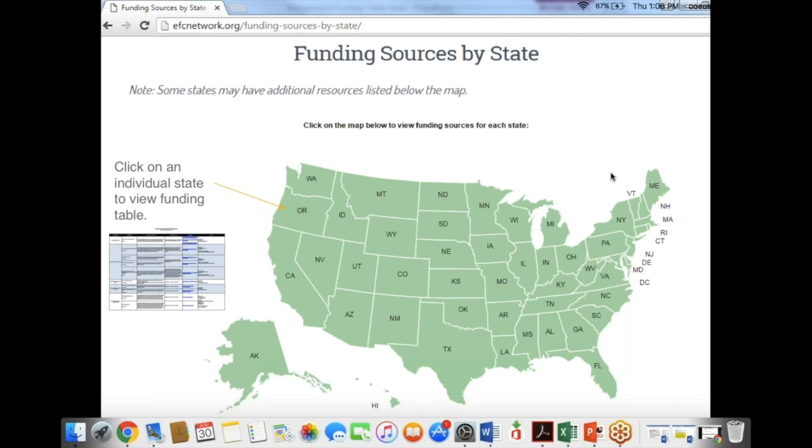And as Heather and I were discussing this prior to the webinar starting, one of the things that's really good to do is ask what's an area where you've got a problem that needs solving, and that might be a pump, or it might be some valves, or it might be a bore or a well, could be a tank, and start where you've got some urgent need or some problem, and do some inventory there and some condition assessment and maybe some work history, gather that up and do a little study on that, and that will get you going.